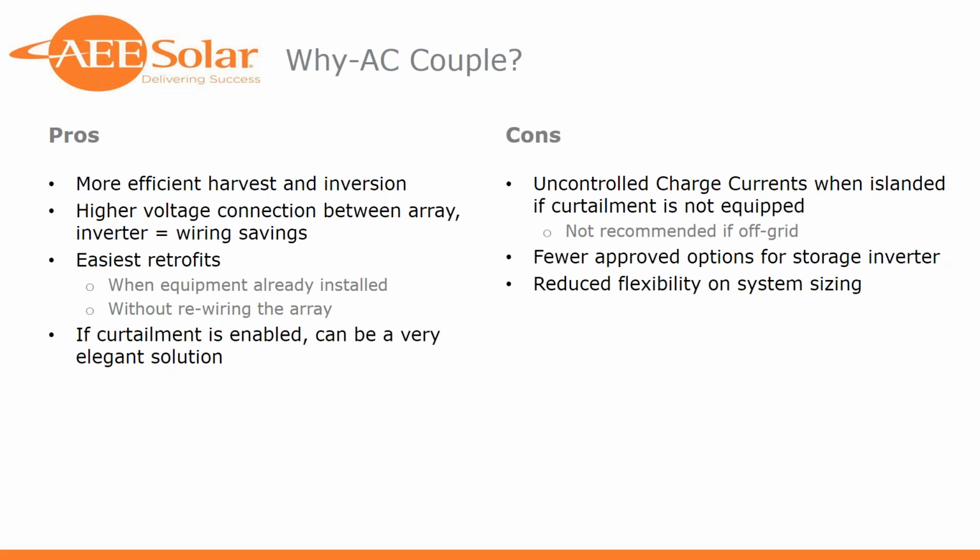That battery, it's going to kill itself. If you've got a 100 amp hour battery and you're regularly presenting it with 10 or 20 amps of uncontrolled charge current, it's going to have a really short life. And we don't want to think about batteries as disposable. We want to size the system properly the first time so that A, your homeowner has a good experience, and B, you get the most life out of your battery bank.